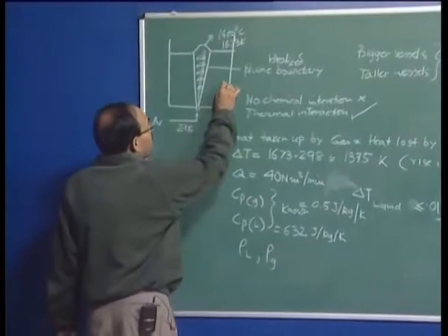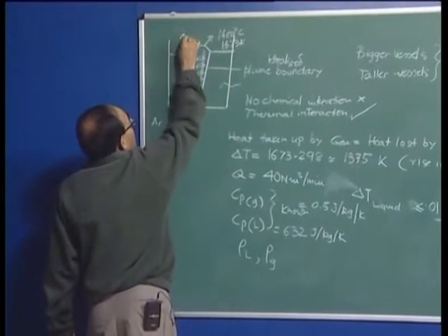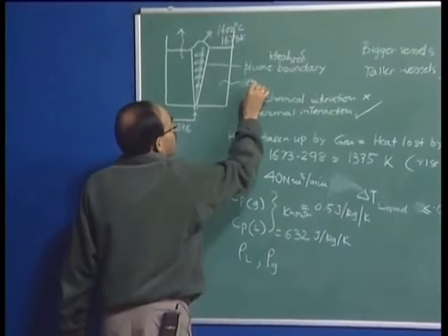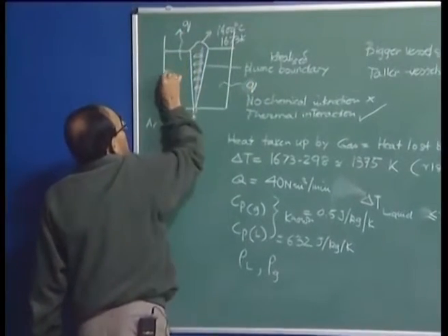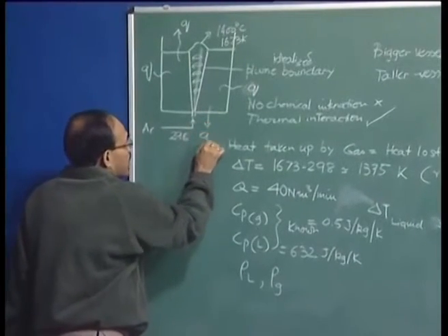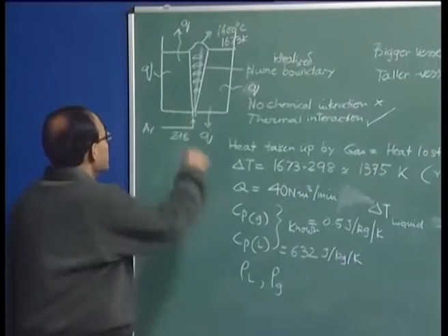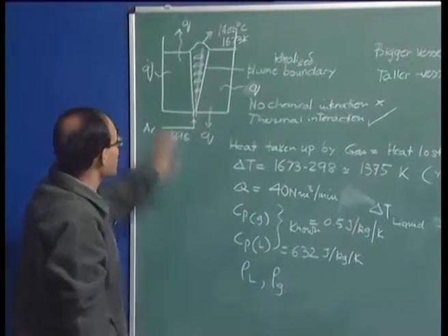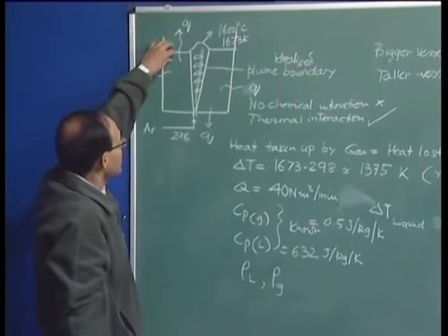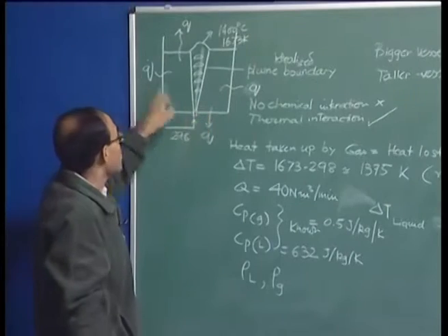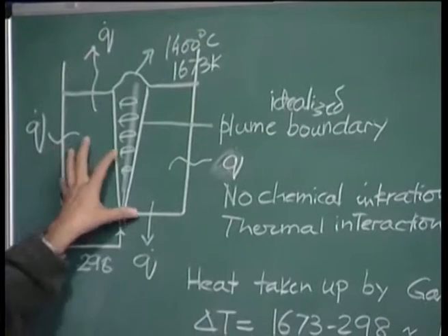In fact, the heat loss through the free surfaces, I can say Q, this is a standard notation. So through all these surfaces, heat is going to be lost, and the loss of heat through the surface of the ladle, the free surface, as well as the bounding walls, the refractory lined walls of the ladle, is going to cause a noticeable drop in the melt temperature itself.